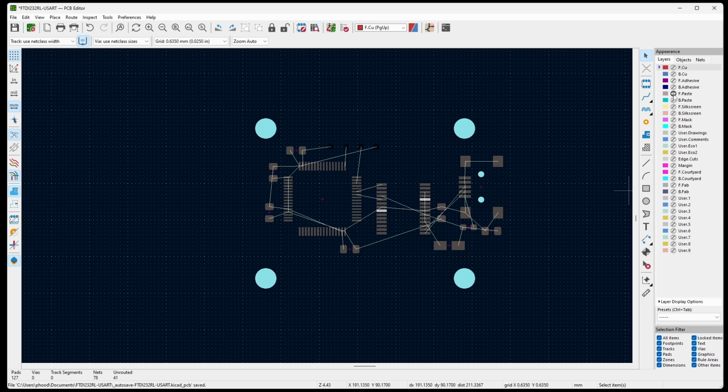The paste layer is where only solder paste will be applied. And this is the layer that PCB manufacturers will use to create a stencil so the paste can be applied using the stencil. It's also important to understand the thickness of a stencil because of the aperture sizes for a microcontroller like this. The apertures are really small and you don't want to get too much paste on there, so you want a very thin solder paste stencil. Because if you have a thick solder paste stencil for pads like this, then you risk the possibility of pins bridging when they're being reflowed, or the solder is being melted.